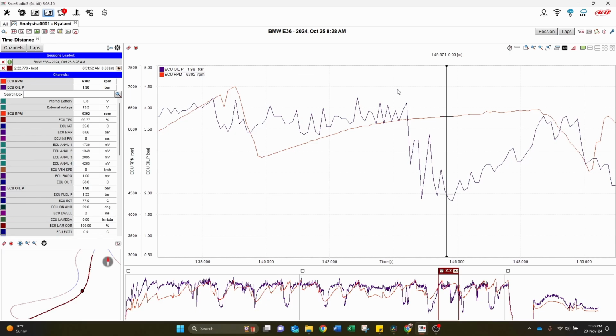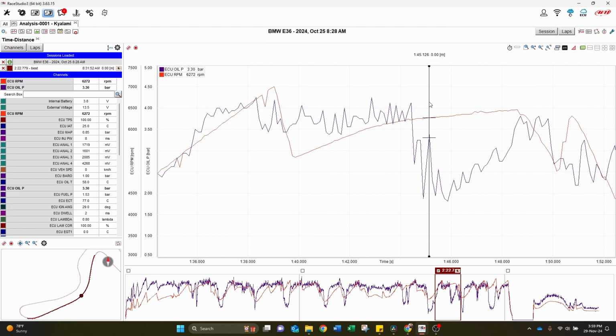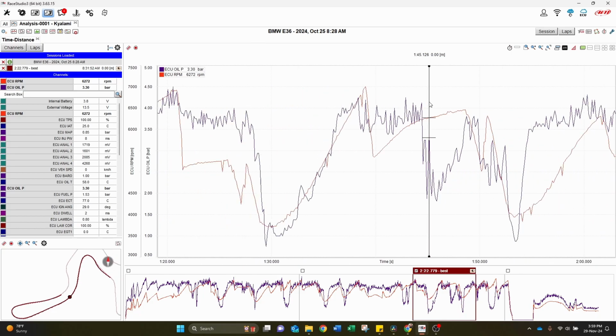So in other words, it must happen so quickly that the oil is there and then it pushes up due to the loads, or it pushes forward due to the braking load. Another thing that indicated it to me is if you look at the oil pressure trace as I turn into the mine shaft, you see that the oil pressure drops away as I turn in, but then it comes back, which means that it is sloshing, it pushes up against the side of the engine and then comes back. So in other words, the energy of the oil pushes the oil away, but then the energy of the rest of the oil brings it back down. That's why you see the spike come back.